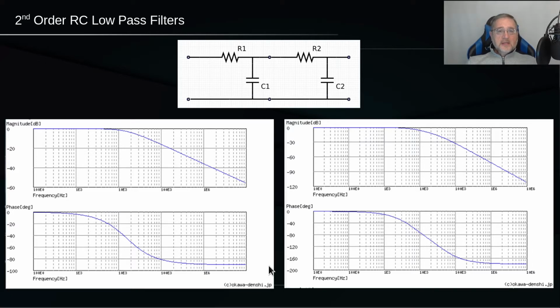The truth is that there is no change whatsoever in the concept. So why the change in the measure of the cutoff frequency then? Well, first, remember that we have defined the cutoff frequency as that frequency where the attenuation becomes exactly minus 3 dBs. We have seen that the attenuation has changed, going from minus 20 dBs to minus 40 dBs per decade.